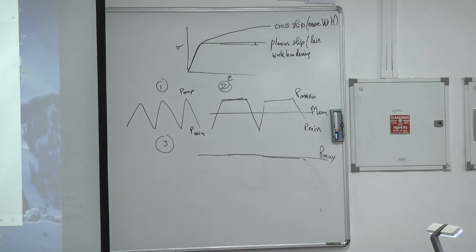But if you have a lot of cross slip, then you see much more striations that are much more easily visible. I mean, you'll see it, but you have to play with it a little bit more, but not a whole lot. I always have a hard time looking at slip striations. Now I don't go to the SEM, but when I used to, I used to see more striations.